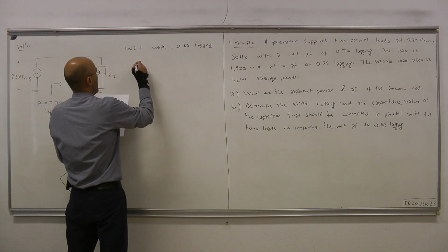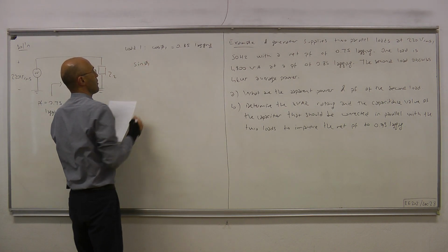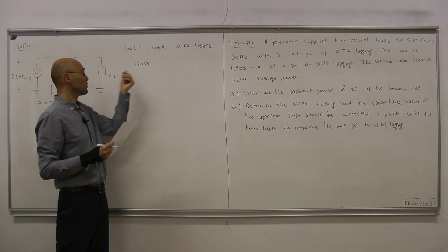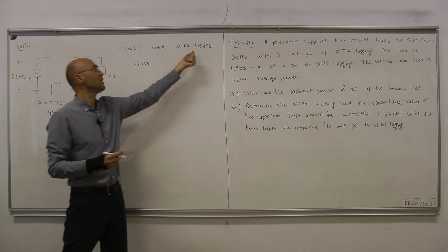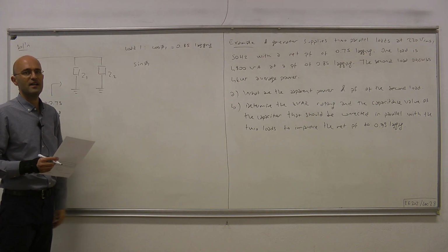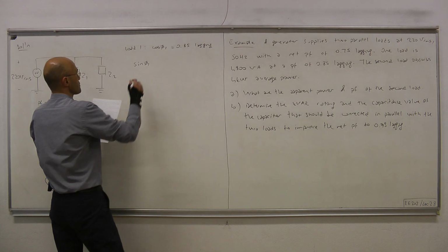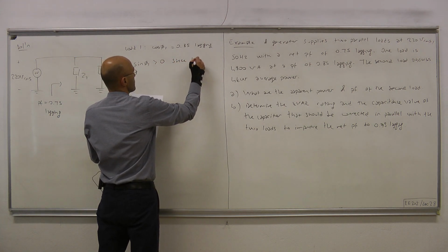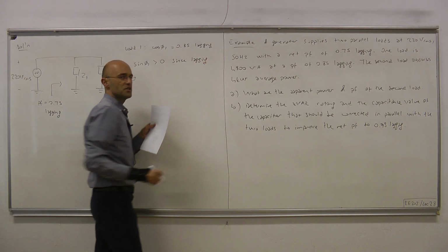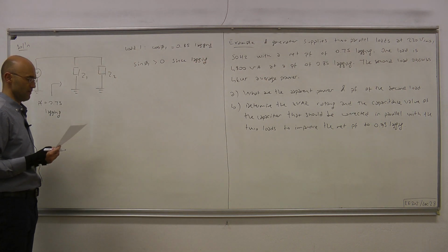Now therefore sine of phi 1 could either be positive or negative, but due to this word lagging, we know that it has to be positive. So sine of phi 1 is positive since the power factor is lagging, or since the load is inductive.